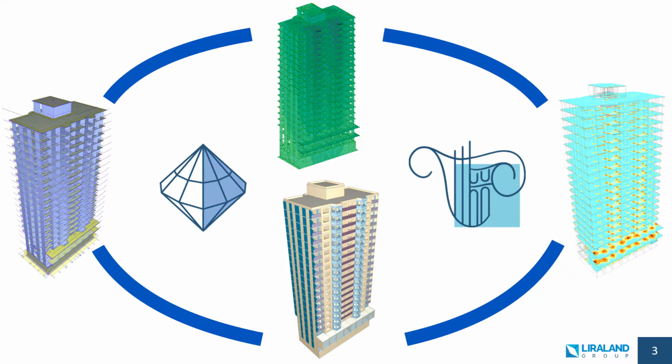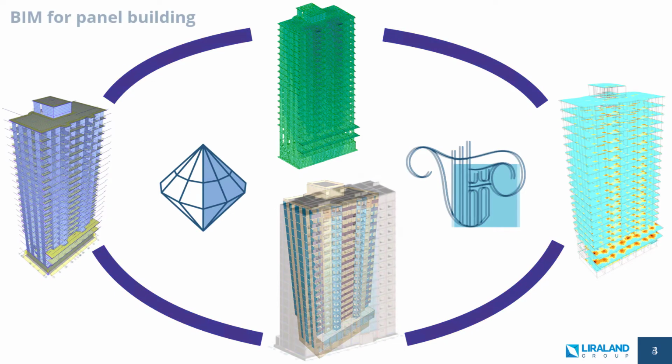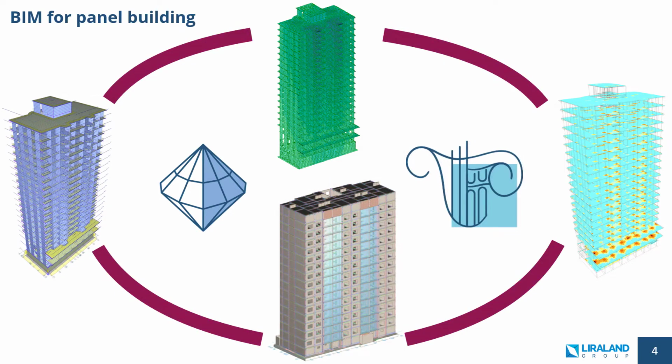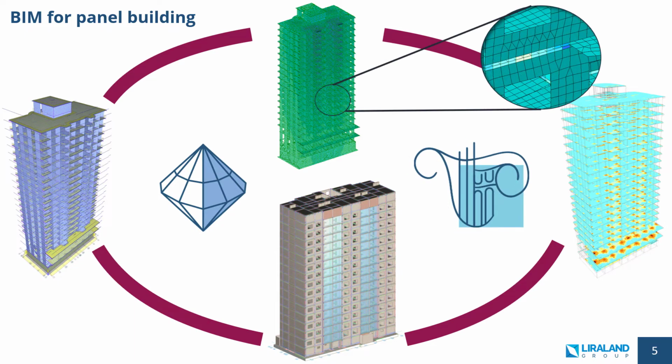The considered chain refers more to cast in situ reinforced concrete, because it includes the design stage. In addition to cast in situ structures, SAPFIR allows you to perform analysis of large panel buildings. For cast in situ building, the main purpose of analysis is the required amount of reinforcement in the load bearing elements. For analysis of large panel buildings, the stresses in the joint elements are our primary interest.